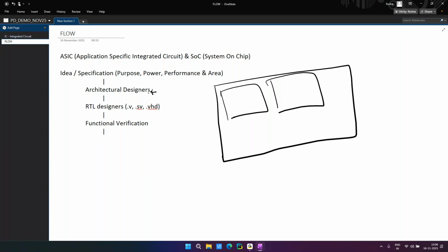So whatever code I have written, I'm going to be functionally verifying it. Functionally verifying it by using multiple test benches or UVM format. There are different languages for that again. By using the equivalent tools, we will be validating all of that. For example, I think Questasim, there are certain tools like that. By using that, we will validate the functionality of this RTL code.